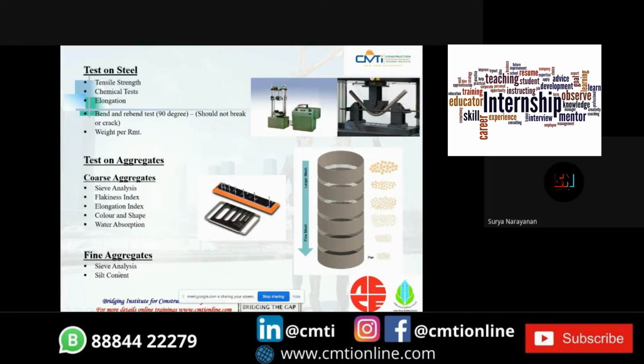Fine aggregate testing is also done using sieve analysis, in the same way, where we arrange the sieve sizes below 4.75 mm in descending order. A silt content test is also done on fine aggregates.